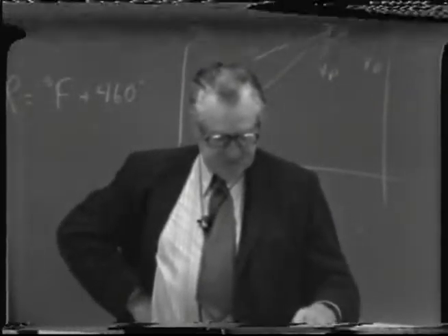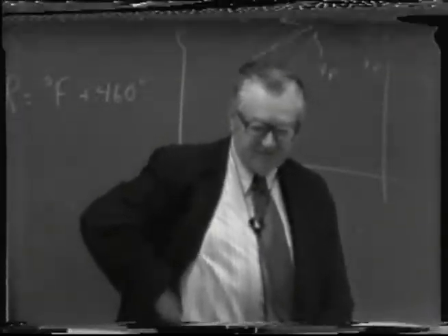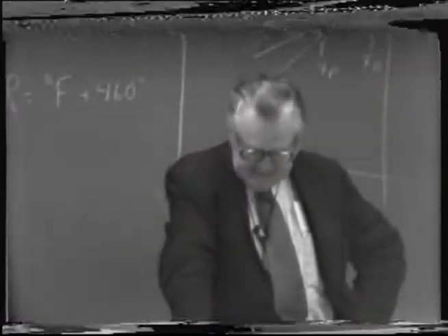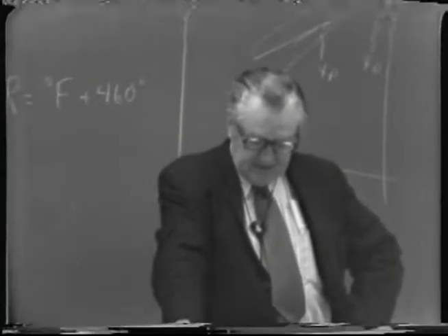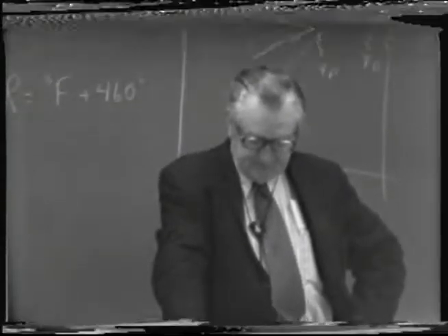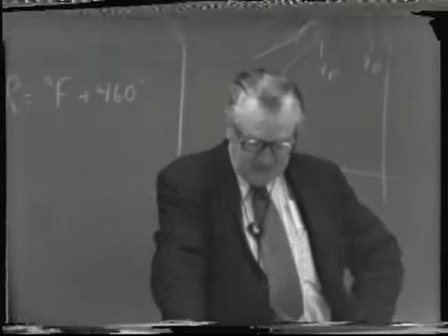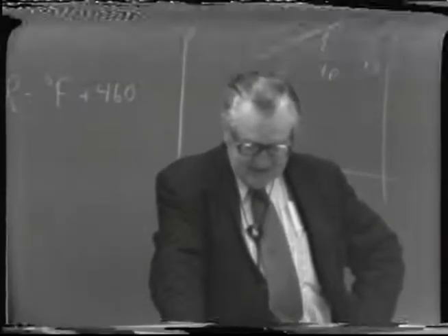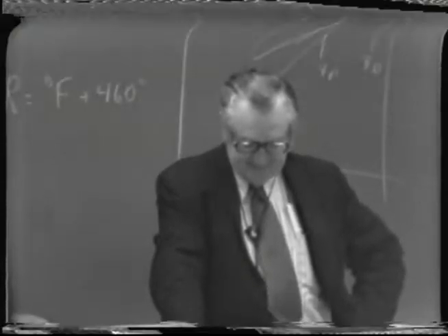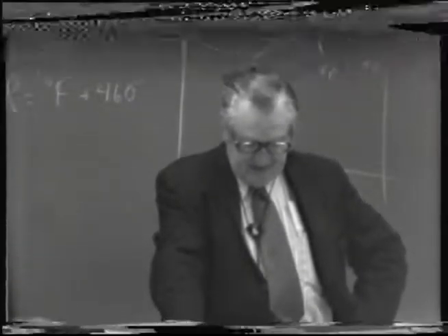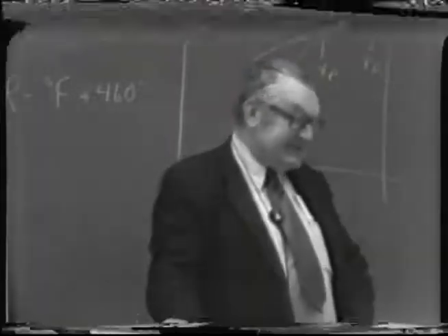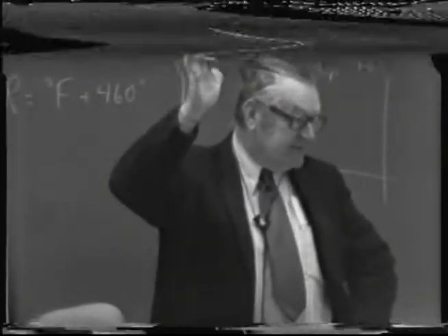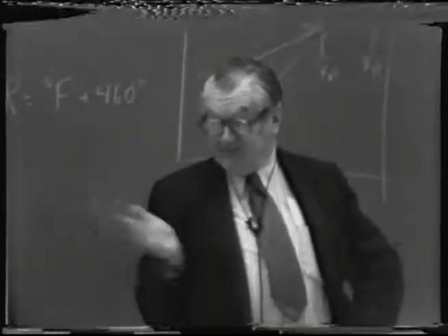Now, to get the diameter of the stripping section, we need to calculate the vapor rate in that section. And so, we can say that first of all, at the base, if we're using live steam, the vapor rate, on a mole basis, is the steam rate, because that's what the initial vapor is at the base.